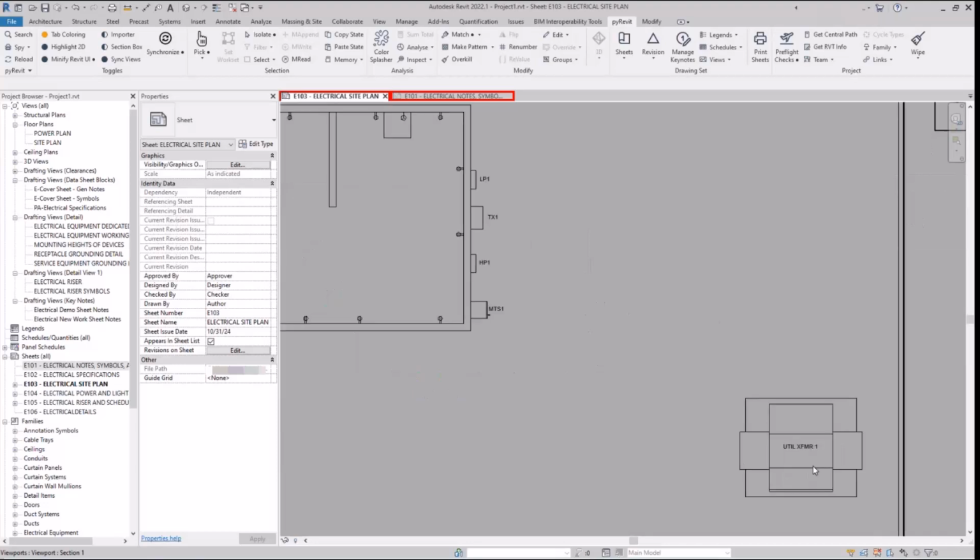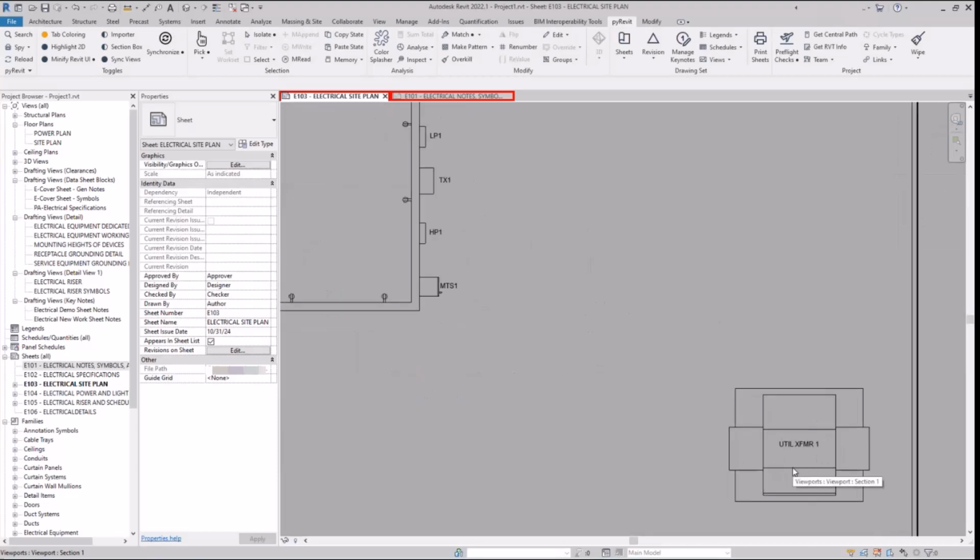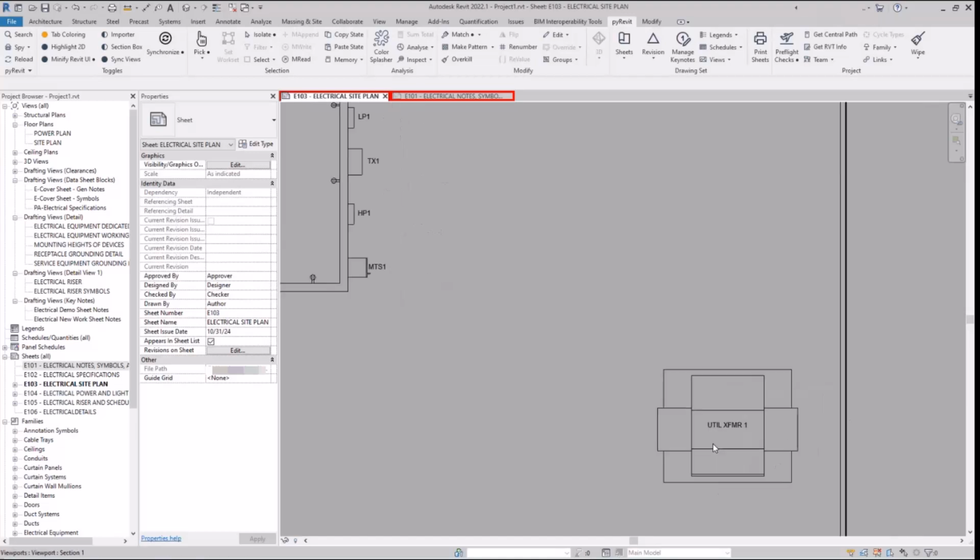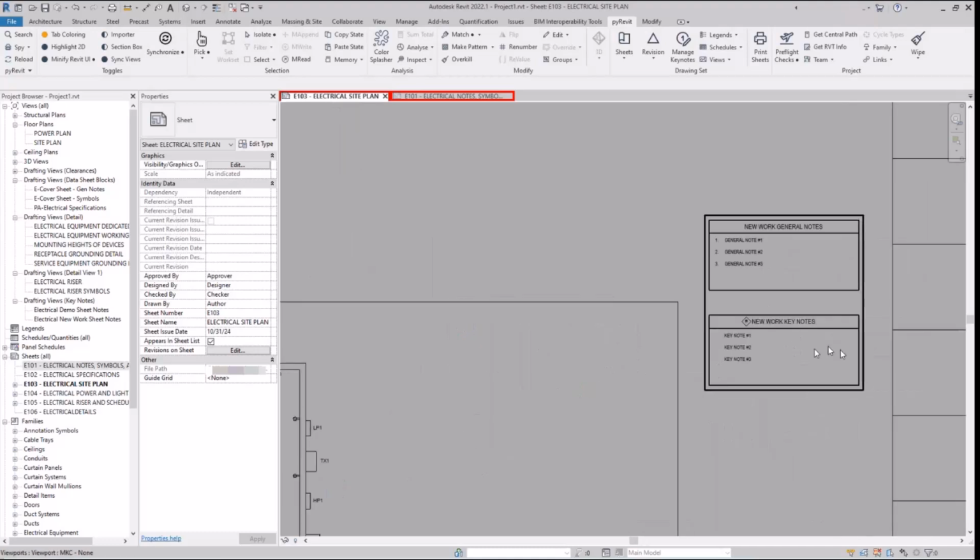Like, okay, utility is providing the transformer. EC, you're going to provide from this point all the way to that point. Normally it's two 6-inch conduits coming in for the medium voltage side, and then however many conduits coming out. And you also have a pad mount, the pad that this thing is mounted to. 80% of the time, I'd say most ECs understand that, but to have it written out in the key notes in the contract document somewhere is very helpful.